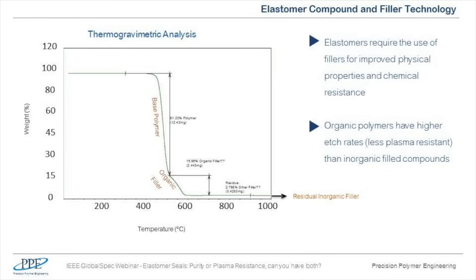It is basically a very simple device. It has a very sensitive balance sitting in a furnace, and we heat up the material up to 1000 degrees and monitor the weight loss, and the weight loss profile gives us very important information about the type of the filler.